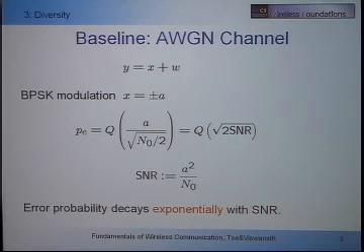It's the ratio of the amplitude and the noise. And I define this by a very key parameter, the signal-to-noise ratio. Signal-to-noise ratio is defined to be the energy of the signal divided by the noise, A squared over N naught. All right? So the first thing to observe is that if I increase my SNR,